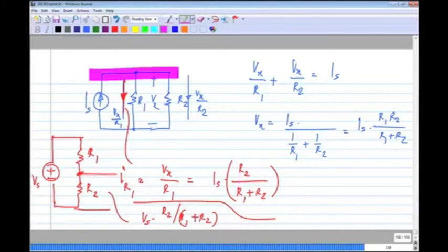Now the next question is, actually the question is not clear. I guess the question is what to do with dependent sources when you apply superposition. You don't do anything. You certainly do not set dependent sources to 0. Dependent sources will have whatever dependence they have. Okay. For instance, a voltage controlled voltage source will be dependent on some voltage Vx. Okay. And let's say it is some k times Vx. You don't change anything here. You simply do the analysis as usual. Okay. So if this is Vx, that is k times Vx.